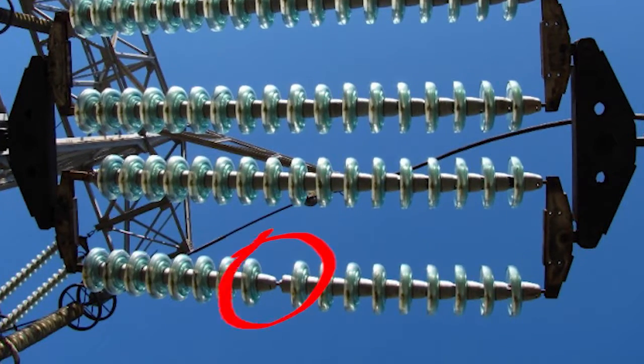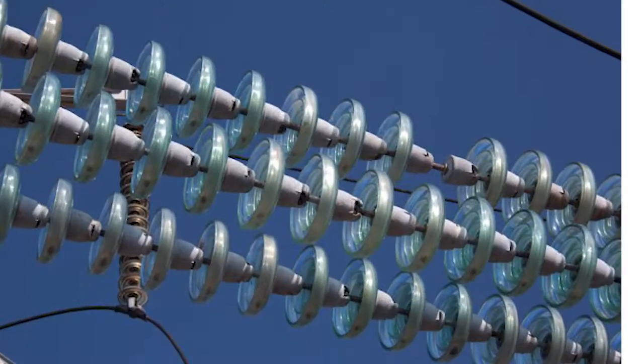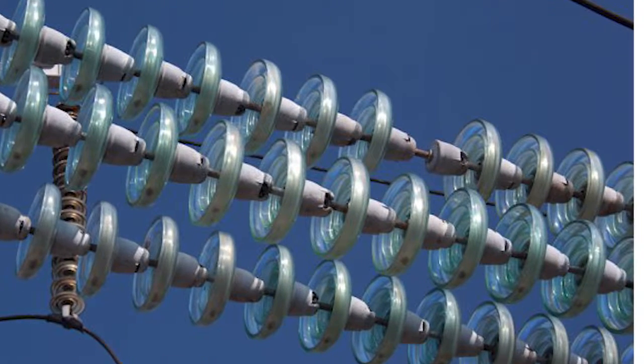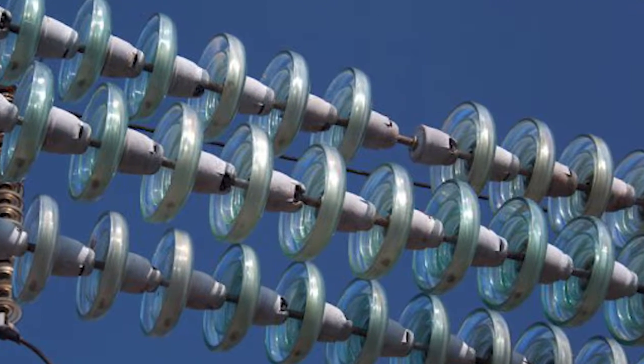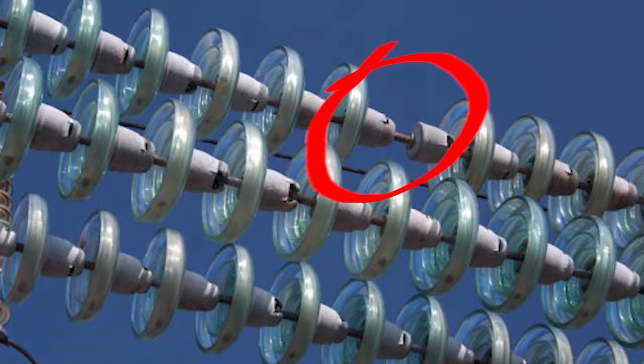Visual indication of puncture is the major advantage of operation for glass insulators. Let us emphasize, destructed insulator is visually identified in a string, and insulator residue keeps practically the same strength characteristics as intact insulator.